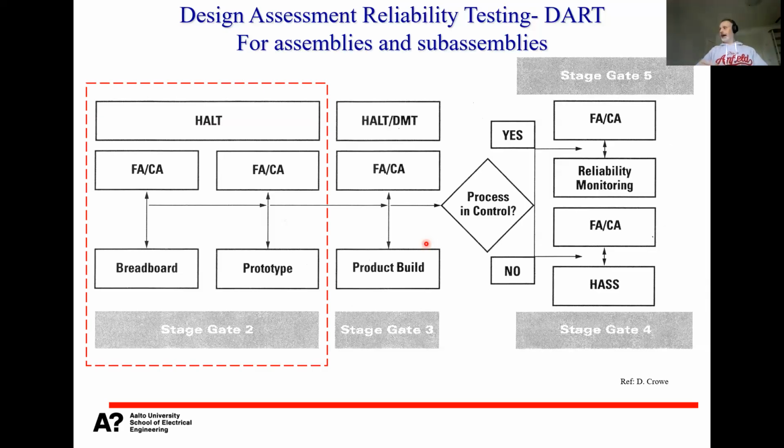Not sure if you see my example, but basically this would be a printed wiring board, and it's completely different if you arrange your components evenly on the board when you start vibrating it, or if you have a high mass concentration at the center.